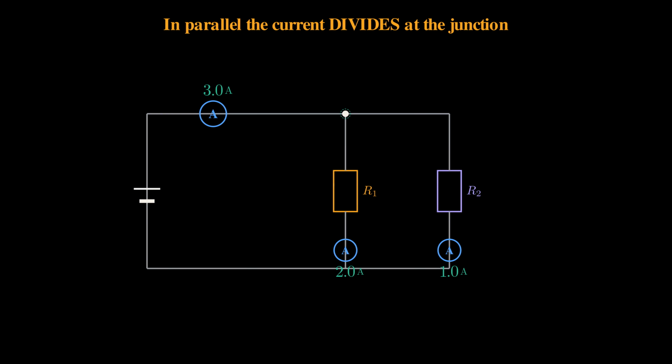And here is Kirchhoff's first law made visible. The current into a junction equals the current out of it. 2 plus 1 equals 3. Charge is conserved. Nothing is lost at the split. His second law says the voltages around any complete loop add up to the cell's EMF. Those two bookkeeping rules, current at junctions and voltage around loops, solve every circuit you'll be given.